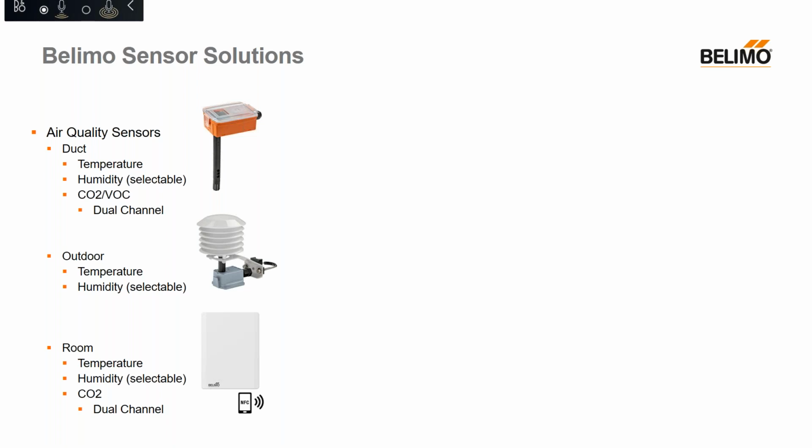Another huge benefit here is that on all of our humidity sensors, you have the option of selecting either relative humidity as an output or dew point on the device itself, either through jumpers or NFC communication. Within our duct and outdoor humidity sensors, you're also able to choose between absolute humidity as well as enthalpy, which means on those devices themselves, you've got relative humidity, dew point, absolute humidity, and enthalpy all selectable within the same device.